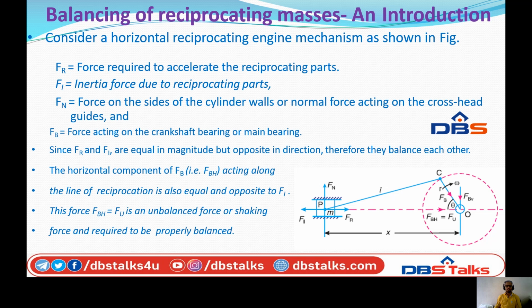These inertia force and reciprocating acceleration force are equal in magnitude but opposite in direction. In the diagram, Fi is towards the left-hand side from the piston and Fr is towards the right-hand side from the piston.